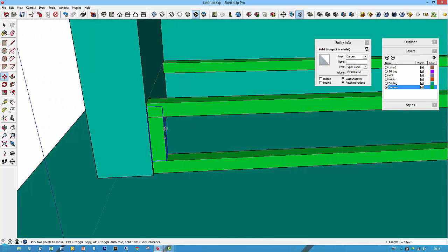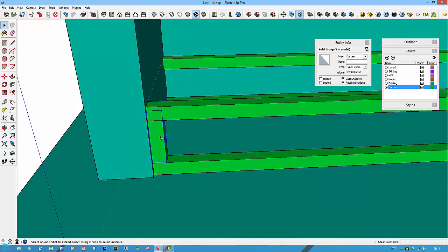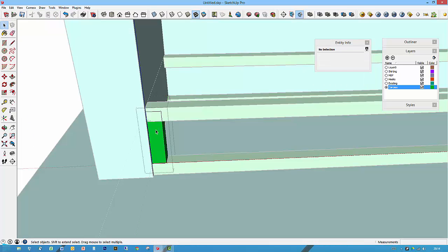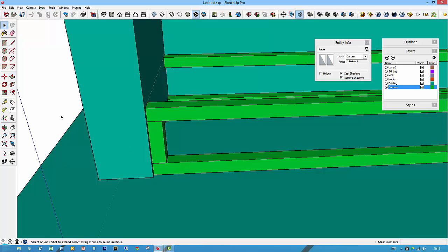All I'm doing is just roughly positioning these things and then I'll do some fine-tuning in a second. So again, position that there, and just to show you that you can push-pull through things, double click on this, P for push-pull, and I can't see that top edge, but I know it's there, and I can just click and drag to that point.